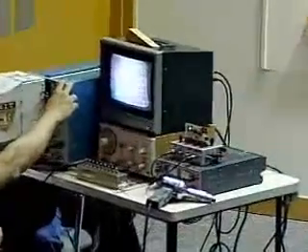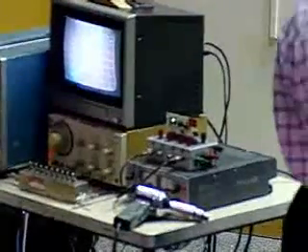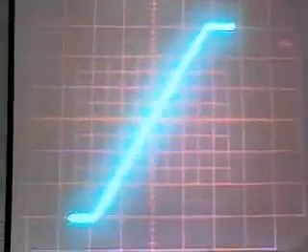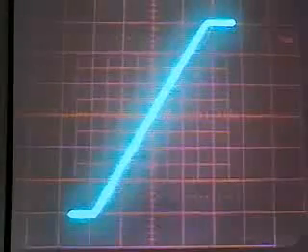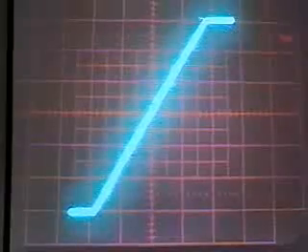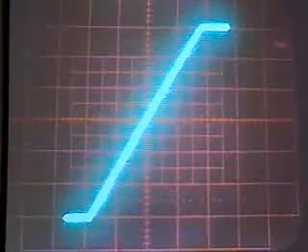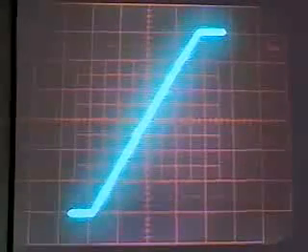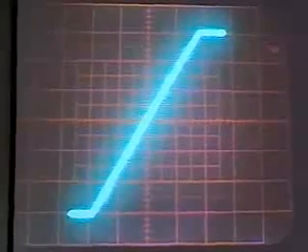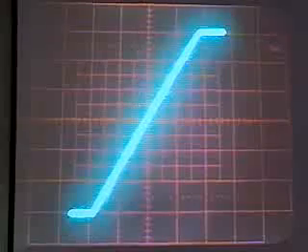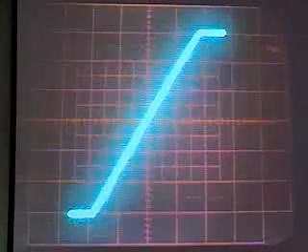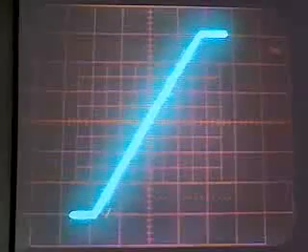So this time around, this is the transfer function, the V naught versus V in. I notice that this time around, I have similar scales on the x and y axes, and this has a slope of 10. This is the point where the amplifier saturates at plus 12 volts, and this is minus 12 volts, and this point here is 0. So this is V in, V out, plus 12, minus 12, and this slope is 10.